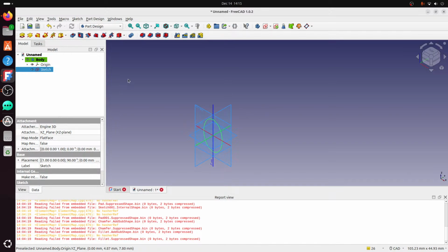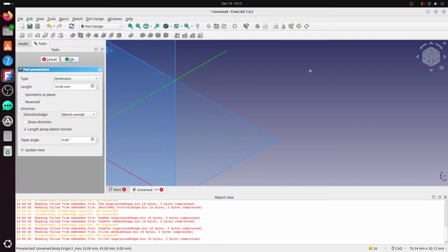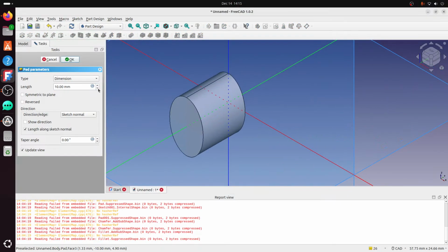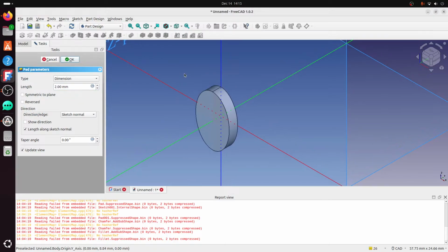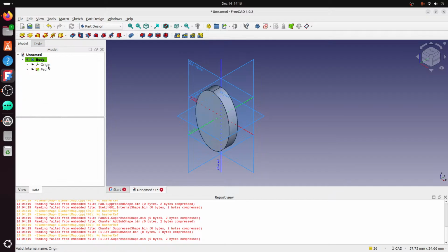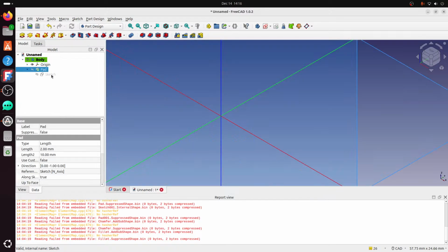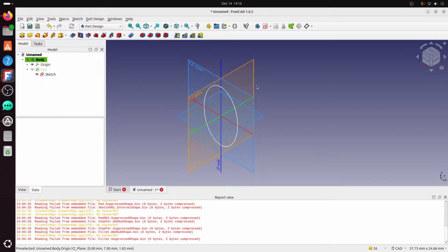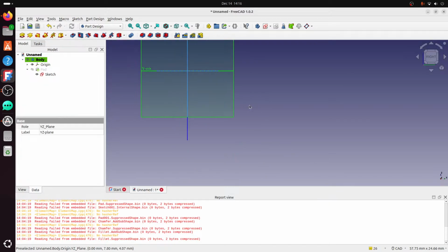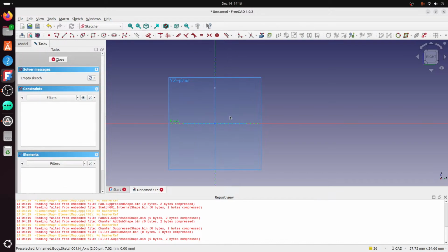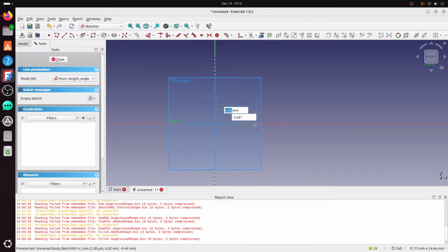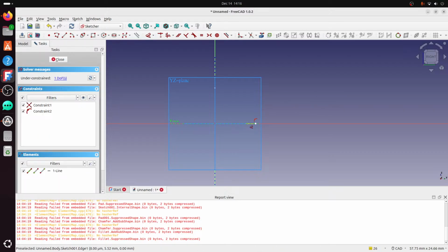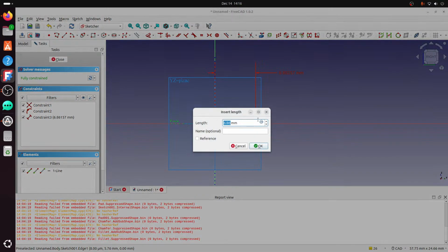But I think I'm gonna do a small pad. Like 2 millimeter. Yeah. And then hide that, show that sketch. And then do a sketch. Like there to there. And this is going to be a micro crankbait, so I want it to be like an inch long. So we'll do a quarter of the length.